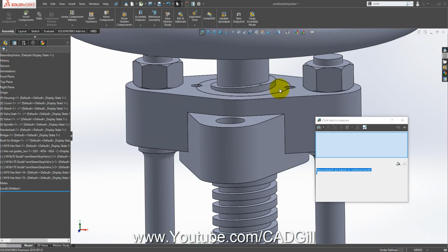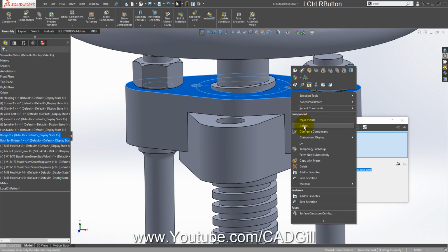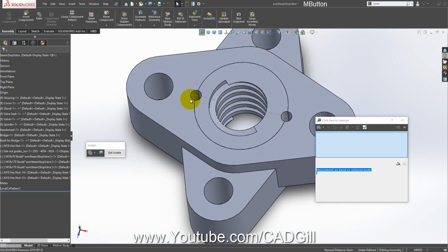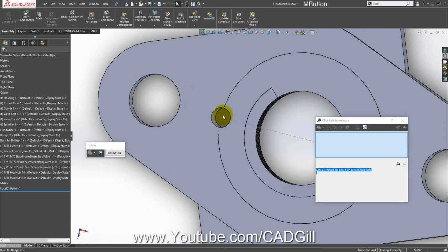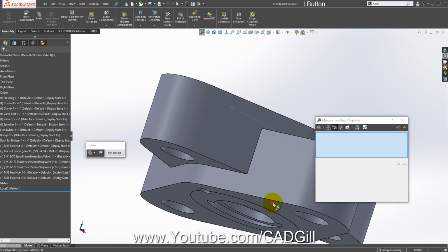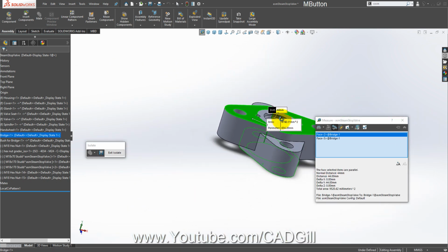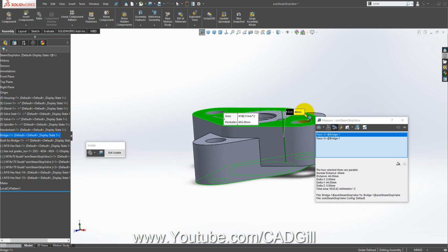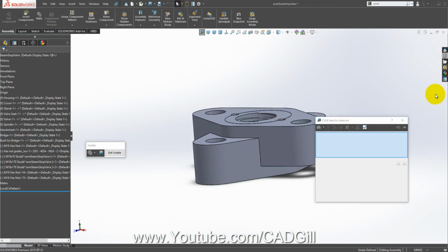Okay, now about this part. You can see that there is an M8 tapping here. We have to add some bolt here also. Let's use grub screws here. So M8 into 44 mm grub screw. We can use 40 mm also.